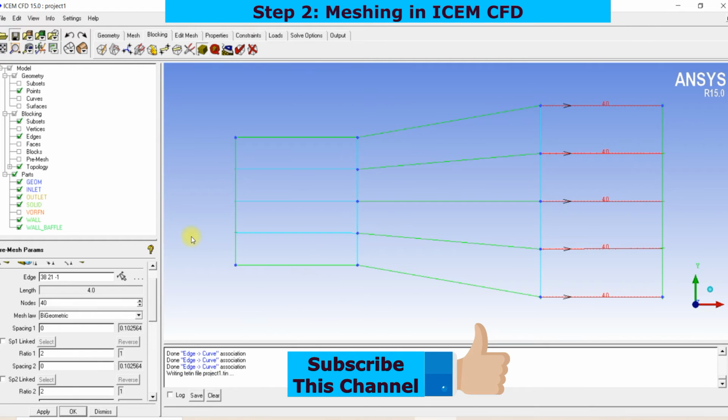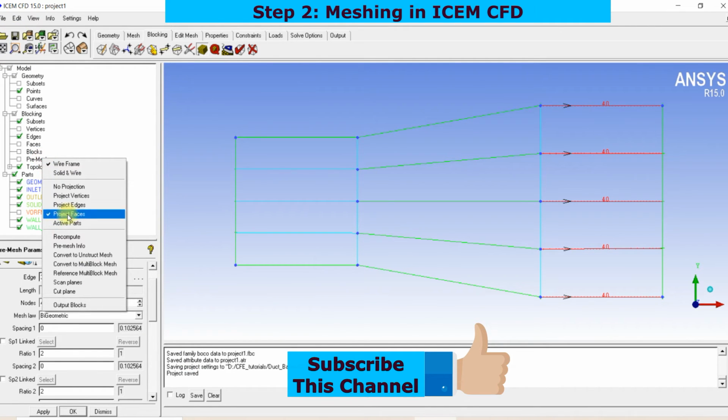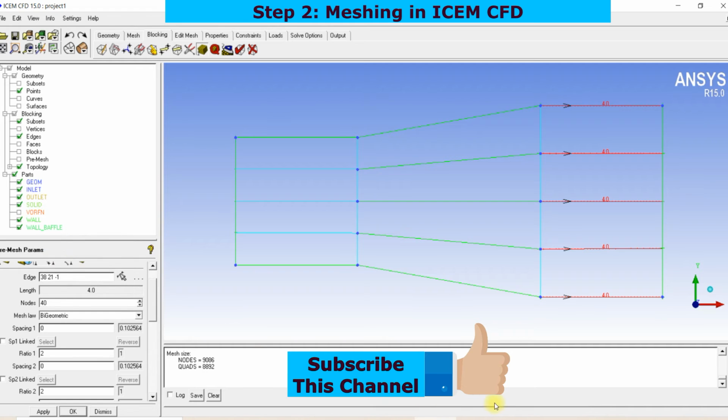And save the file. You can show pre-mesh information. Here the pre-mesh information means 8892 elements will be created. 8892 cells will be created. That is the prediction before the computation.